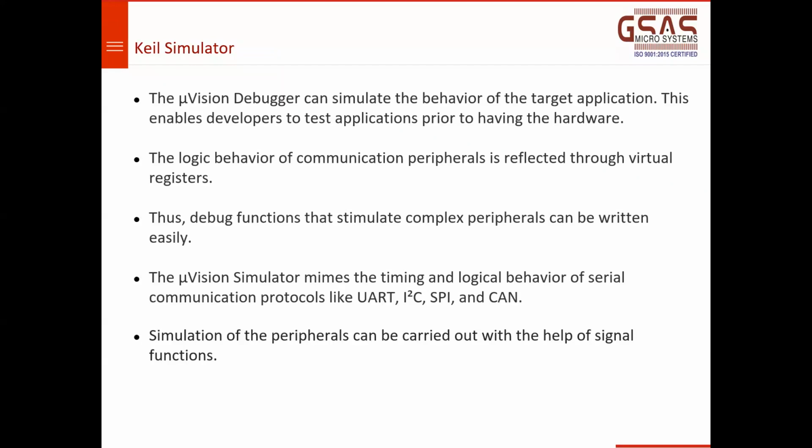Simulation plays a vital role here. What the simulation does is, even before your hardware is ready, software developers can develop software in the Keil and test it on the simulator. So the simulator is a virtual target. It means there is no hardware present, but still you can test all the functionalities of the code you have developed. In that direction, ARM has focused, or is investing highly in resources, to develop the simulation models.